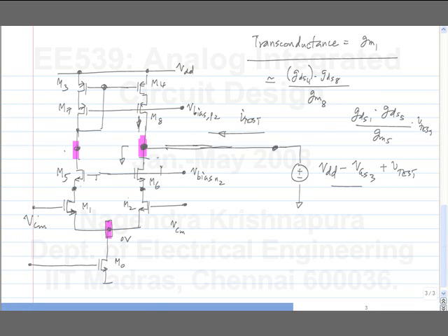So we will do it partly. The actual output resistance of a common gate amplifier, if I was looking up here, I also get these two terms. But these two I always neglect because that gives me unnecessary complication in the algebra without adding much to the answer.